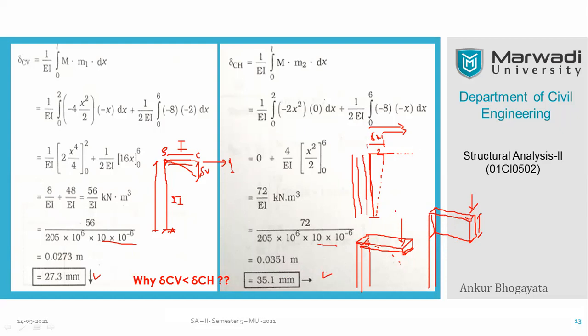But now in this case, let us say point A and point B. Definitely for the same loading, the deflection at point B will be far less than the deflection at point A, because of the limitation of moment of inertia due to cross-sectional orientation. So the orientation of the members is very important for any structural arrangement, so you have to take care.